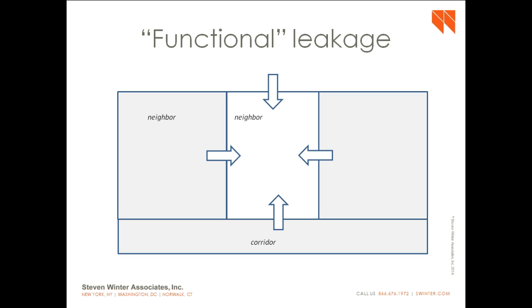Then when this building is put into real operation, those pressures go away and you have prevailing building pressures. If everything is working as it should and your target apartment is at -5, for example, like we had in the example before, and your neighbors are all at -5, some of the leakage between those apartments will be eliminated because there's no pressure difference between those apartments.